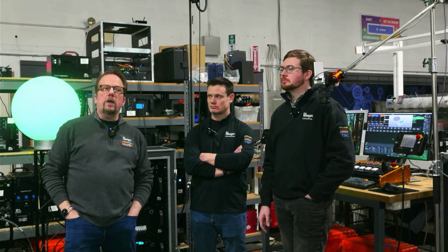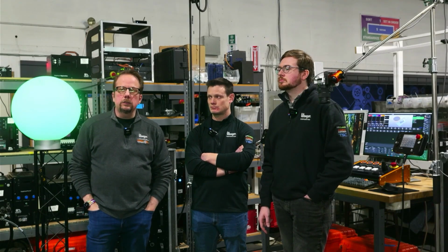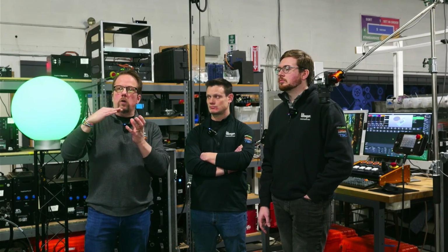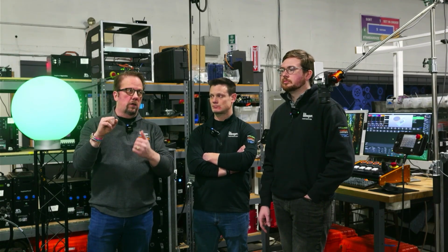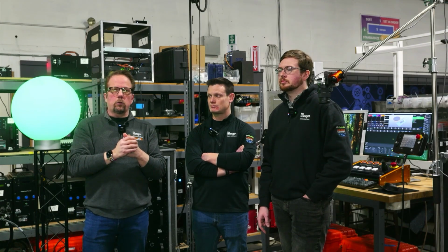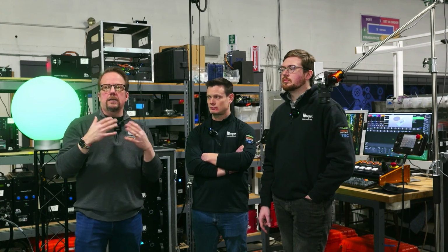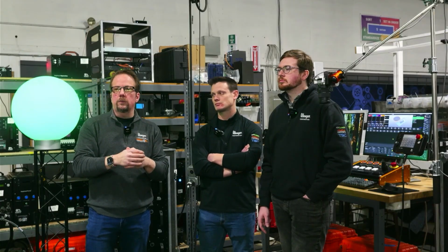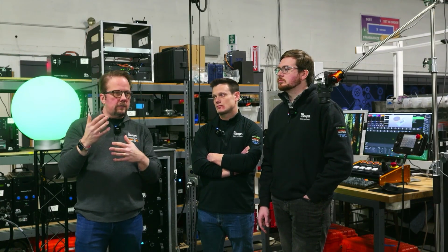If we're doing a retrofit where the hoists exist, we'll be coming in with a junction box and affixing that to the hoist and hardwiring all of your sensors to the junction box, and then there are soft tails coming out of there that plug into the stagehand. The thing that we're mostly religious about is keeping everything connectorized so that it is easily swappable. I say mostly because it's not as though we never do a fully hardwired system. There are some times when that really makes sense, an example that comes up being scoreboard hoists.